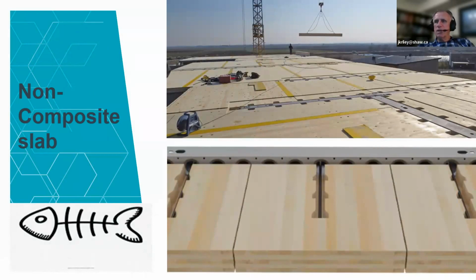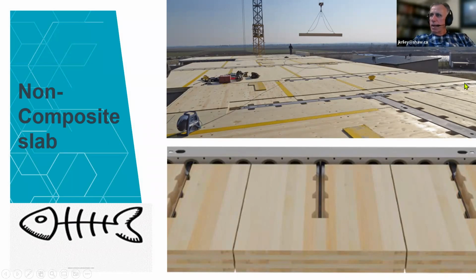Now, non-composite is not very common. We see it not being used nearly as much as it used to be, particularly in Europe, because we've got a lot of issues with fire in that. And so you can see here what we've done to accommodate non-composite design. We have to router out this area. So yeah, what we did is send the Jolly Green Giant up with its king size router to take this area out. And here's where we put transverse fastening rods that fasten the deck to the beam. And then this whole area is going to be filled with cement.